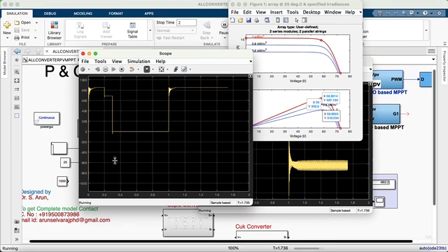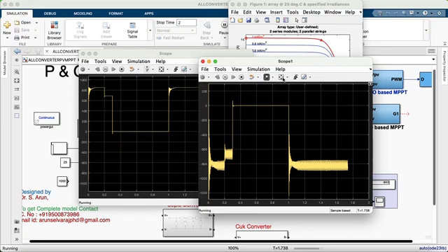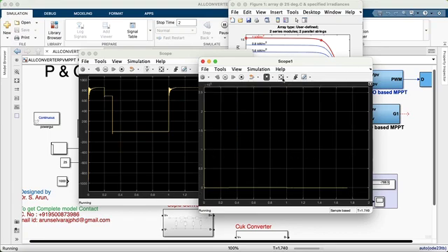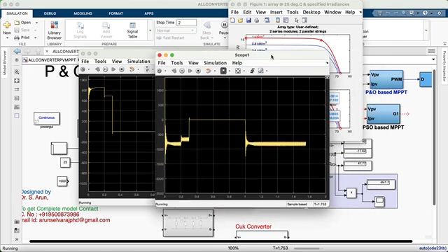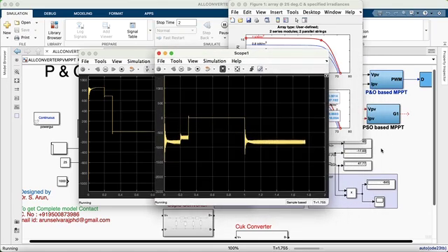During the interval between 0.3 and 1 seconds, the battery power reaches 0. The reason is that when the PV panel is getting the maximum power, the battery is charging, during the period of 0 to 0.3 seconds. When the irradiance level reaches 0, the battery also stops charging. From this time onwards, the battery is ready to discharge power. Here we are only using it for charging the battery. Okay, is that clear?